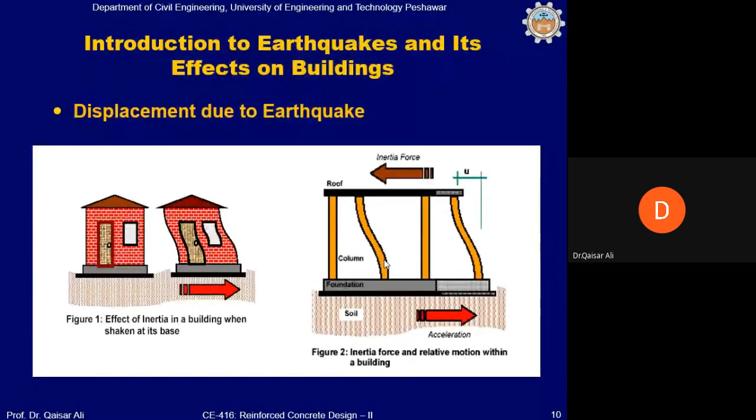One other possibility of avoiding stresses in the columns and walls is that when the ground moves, the foundation should stay at its original position, and this can be done only when the foundation is detached from the sides. This can be done through some technique by placing some soft material, some kind of lubricant or other soft material, between the foundation and the ground. So when the ground moves, the foundation does not move with the ground, which gives rise to a concept called base isolation.